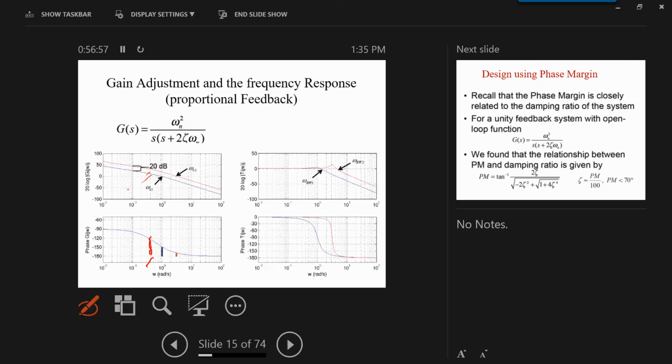Well, it depends. If I am keeping the same root locus, yes, it is a lag control, if I don't have any other specification, just damping, which means overshoot. I have only an overshoot specification.